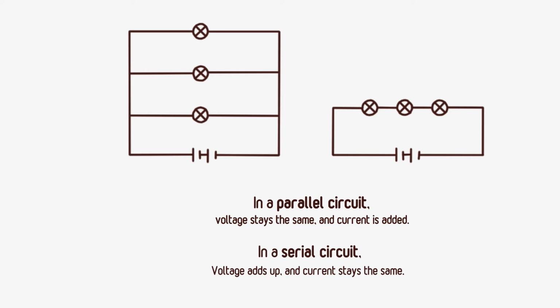But for the purpose of this video, all I really want you guys to walk away with is the difference between a parallel and a series connection circuit. In parallel, all the positives come together and the negatives come together and they join at a single point. In a serial circuit, the positives are daisy chained with the negatives, and you use a lot less wiring.